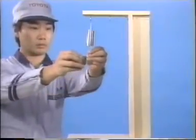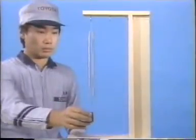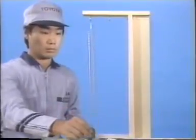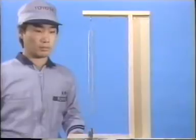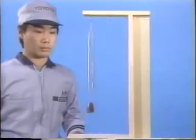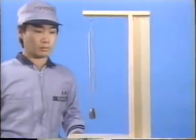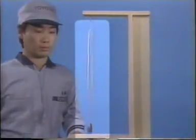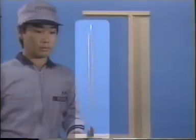We will use simple models to demonstrate the nature of vibration, which just means the rapid oscillation of an elastic solid or fluid. The number of such periodic movements, or cycles, per second is called the frequency. Frequency is expressed by the unit hertz. For example, 1 hertz is equal to 1 cycle per second. These systems, each consisting of a weight and a spring, are called vibrating systems.